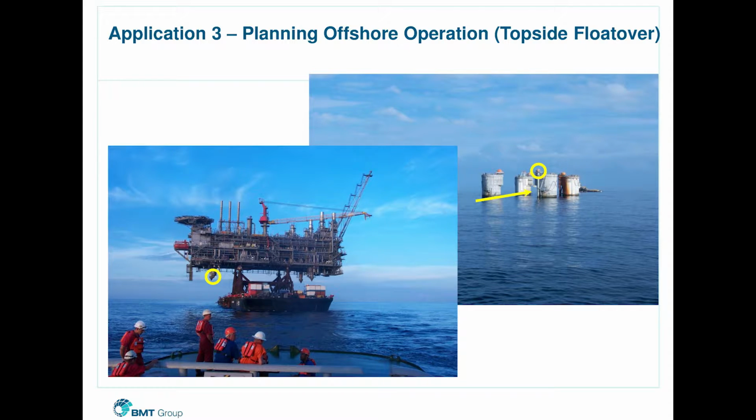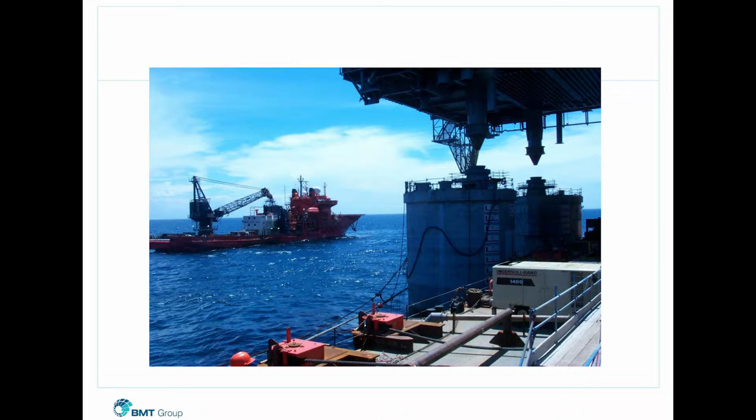And the game is to land that topsides safely on the base. So we've got a locating pin here, and we've got a receptacle here on one of the piles, and all we have to do is float the barge down the middle of those piles and deballast it and drop it down.